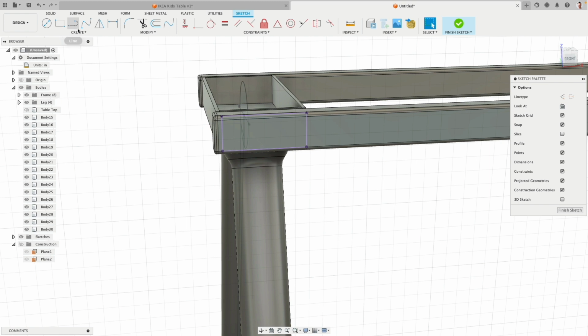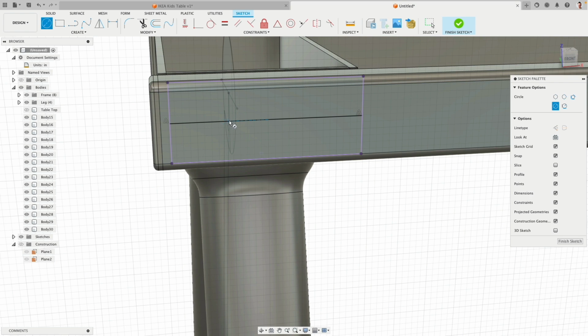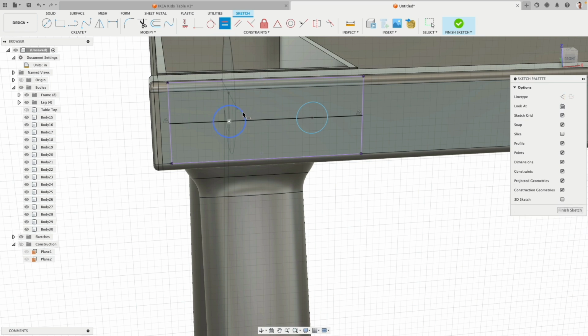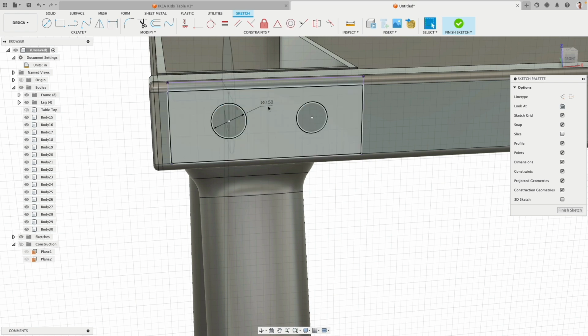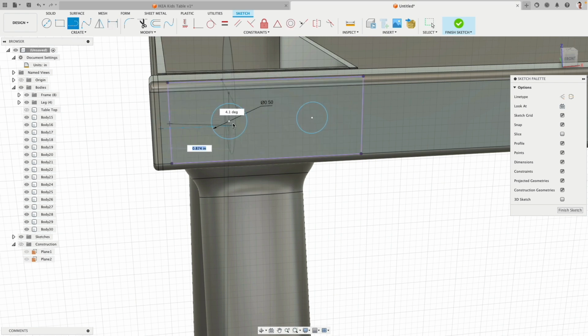border. And then here there's a midpoint, draw a line, and then there is a circle there and there. Let's say these two circles we make equal, and then 0.5 of an inch. How do we do the dimensioning? Oh, very easy. Midpoint to this point, to this point, midpoint. These lines are all horizontal, they're already perpendicular. Very good. Cool. Then I can just make them all equal there.